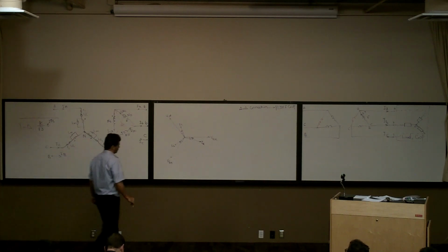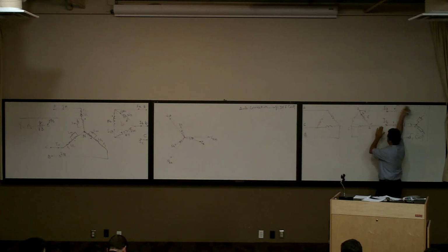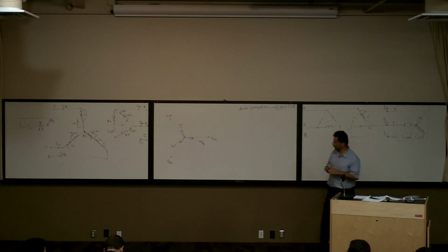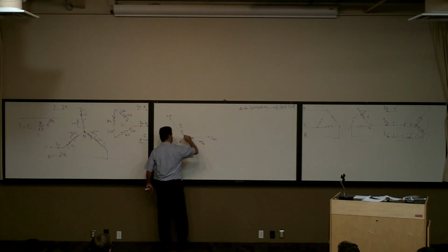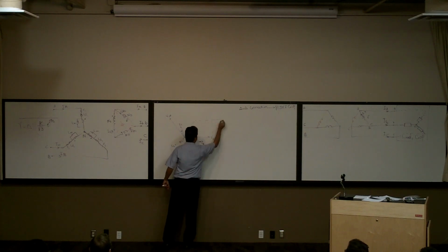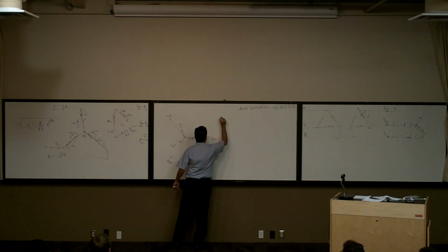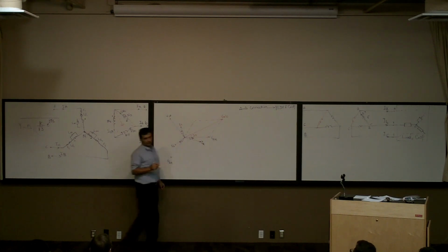Now I'm going to calculate the power from this side. Forget that side. I want to see how much this voltage is. The current is staying the same. Let's look at the voltage here, the voltage VAB. VAB is going to be like this. And how much is this angle? 30 degrees.